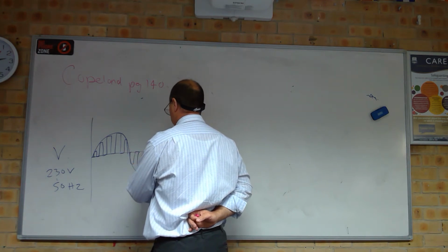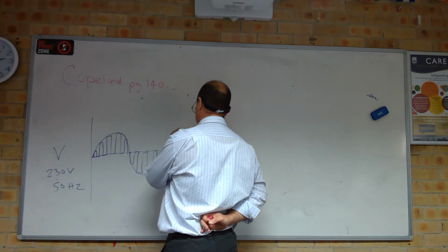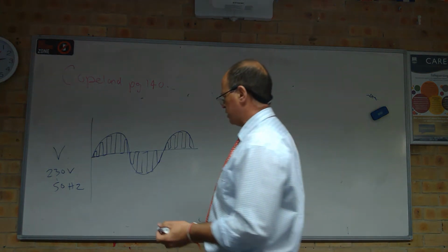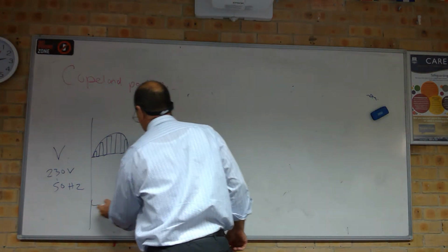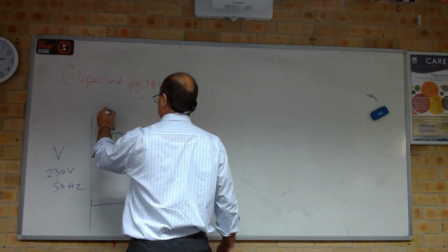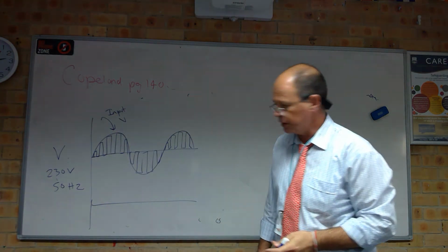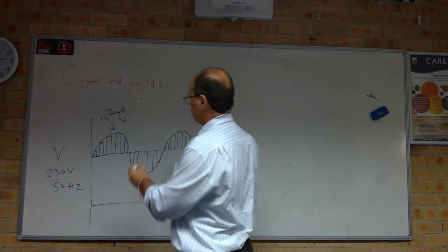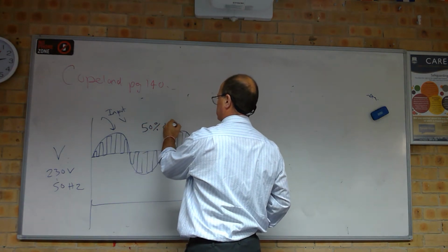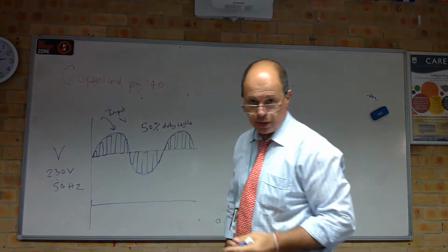So we chop it up in like a 50% duty cycle. We can change the voltage. Now we already know about that. We did that when we were looking at our DC voltage. So that's our input voltage at a given frequency. When we chop it up and we have a 50% duty cycle, we know that we're going to have a lower voltage.